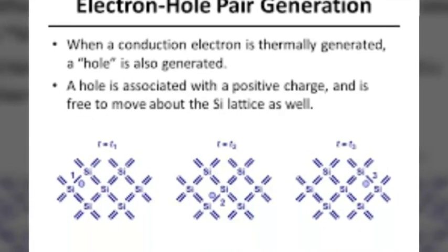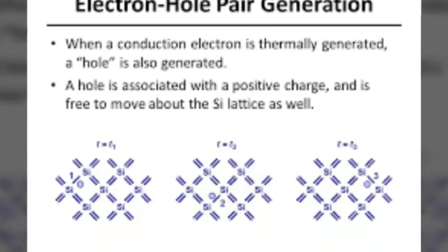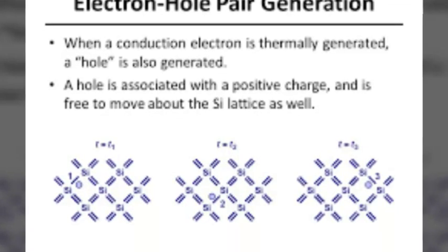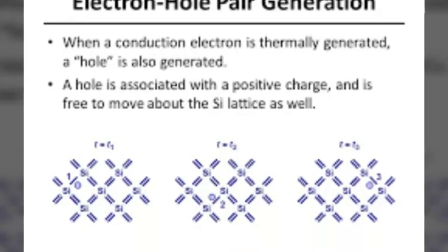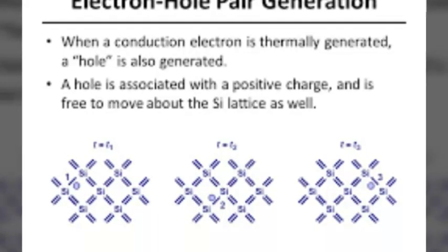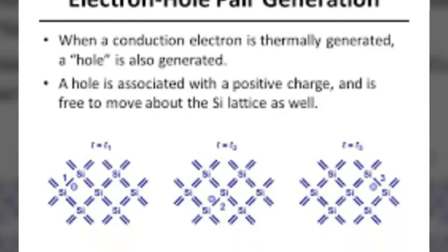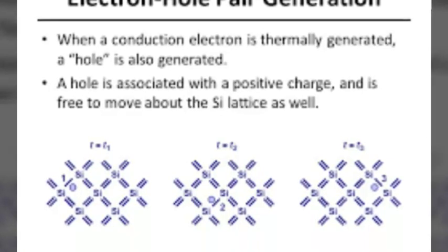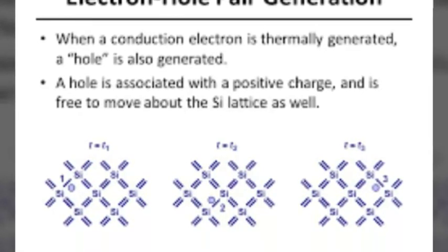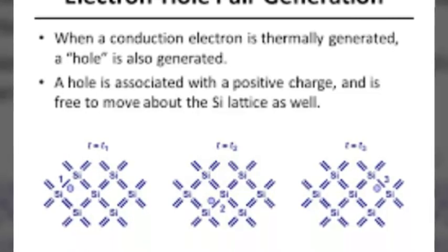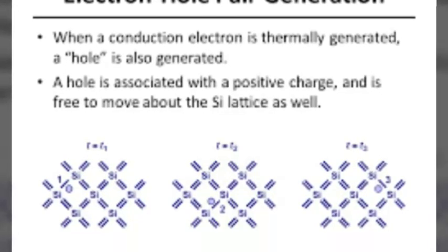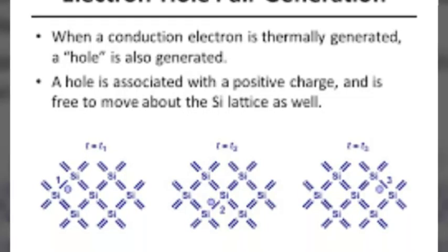Okay, now let's discuss hole current or hole. When a covalent bond is broken due to thermal energy, the removal of one electron leaves a vacancy, therefore a missing electron in the covalent bond. This missing electron or that vacancy is called a hole, which acts as a positive charge. For one electron set free, one hole is created, therefore thermal energy creates hole-electron pairs.